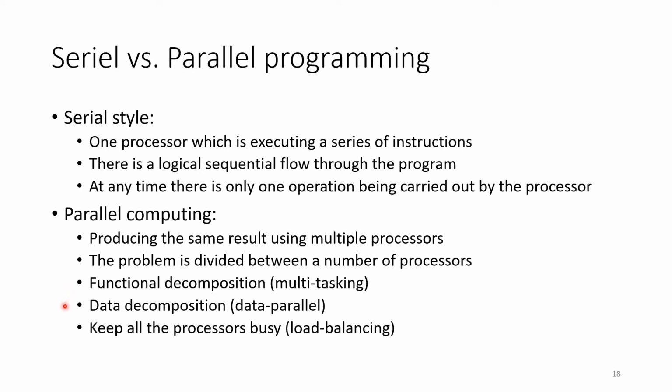So more common there maybe is a data decomposition, which means I have my domain, which I split into 4 pieces, and each of my 4 cores does all the functions. So it will calculate flow, it will calculate temperature, it will calculate solute transport, but just on a part of the geometry and not on the whole geometry, which still means I'm having 4 operations in parallel, so I only need a quarter of the time.